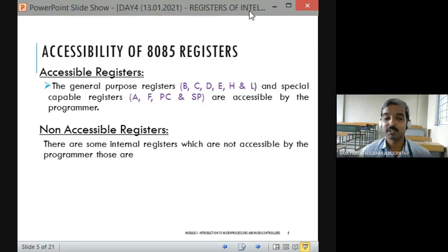See, we have not started programming yet, so don't worry. I asked only to check whether anyone remembers. Fine. Antony Surya typed MOV A, B. The meaning of this is that we move the data in register B to A. Correct? I told you MVI A, some data, we can type it. Clear? That is the instruction used to move the content to the accumulator register. Any 8-bit data I can move to the accumulator with MVI A, the 8-bit data.